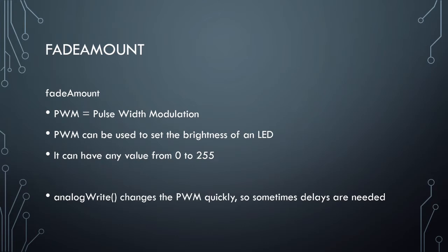And this can absolutely be used with other components. We can operate them halfway or at halfway on, so to speak, but an LED is a really good way to illustrate this. It provides a really visual reference for you to see, and it's a good indicator of if the LED is being analog written to a low value or a high value, or somewhere in between. So we want to have a pin and we want to have a fade amount when we're using analog write. So we specify our fade amount by pulse width modulation, and we give this a number.